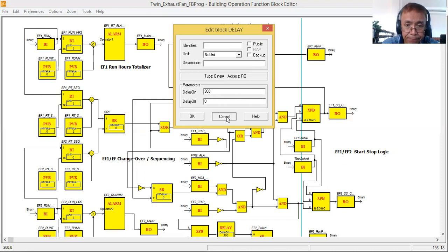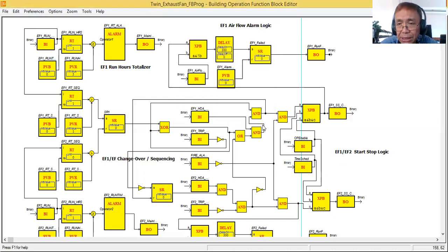Because the one that will be dealing with the BMS system after handing over the project is the BMS operator. The BMS engineer will not sit in front of the BMS workstation. You need only a BMS operator there. So you must make your control logic program flexible so that the operator can make some changes in the equipment parameters.